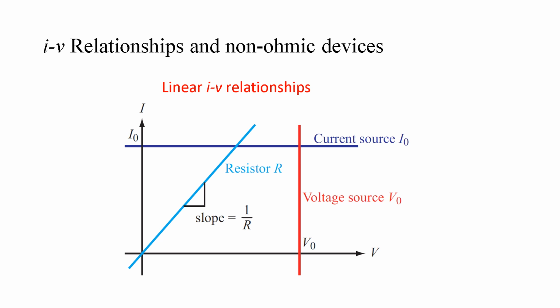This perfect linear slope doesn't really exist, especially when you get to higher temperatures. As you put more current into a resistor, the temperature goes up. As the temperature goes up, that changes the resistance. You just keep spiraling this, and you start to get nonlinear forms in practice.